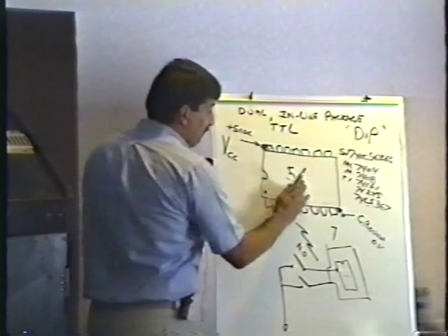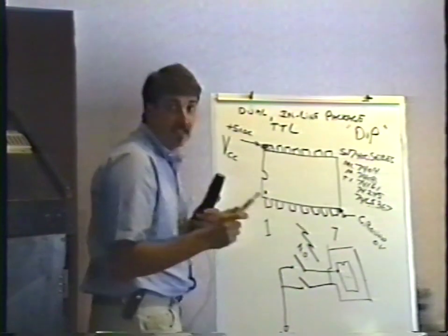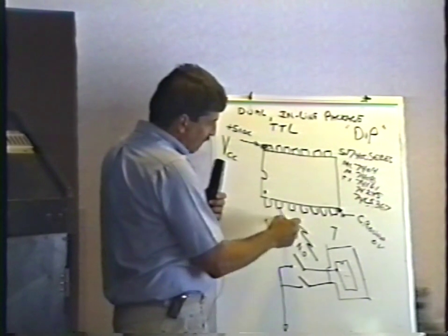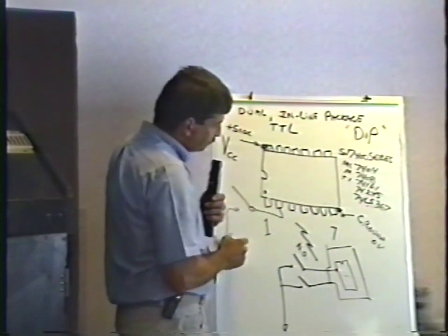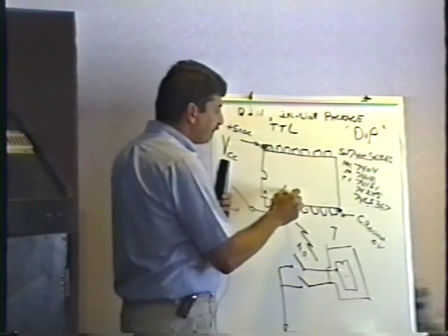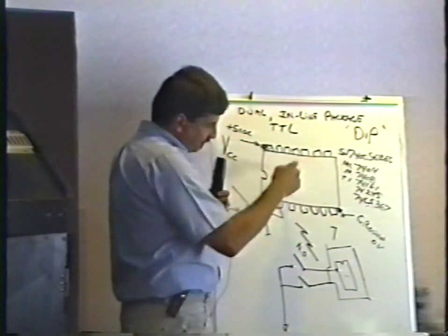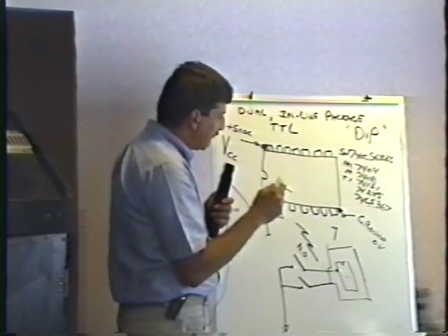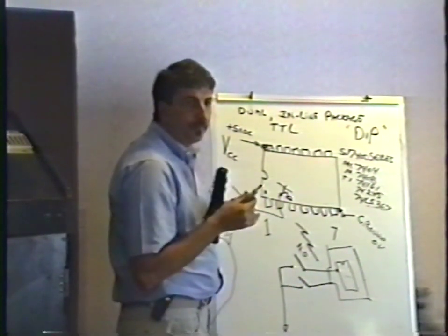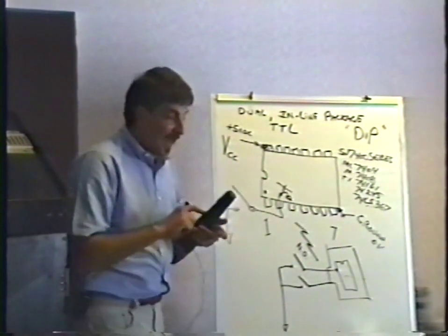What it does, though, fortunately in a way, is that the inputs almost always short circuit. Let's say that this goes to a switch somewhere like this. Inside this chip, there's a mess of transistors, thousands of them, really. And what happens is this input will short to ground. The symptom that you get is this.